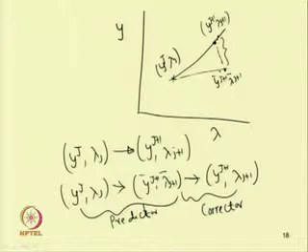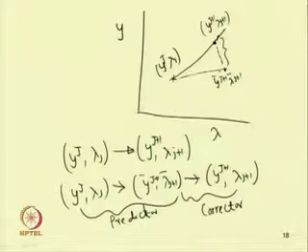While finding this fixed point response solution with change in control parameter, we may have a single control parameter, like the detuning parameter in case of the Duffing equation, or we may have multiple parameters. For example, we may use the forcing parameter f or the detuning parameter sigma in the Duffing equation. In that case it will be a two parameter control space. So we may have a single parameter control space, a two parameter control space or a multi parameter control space.